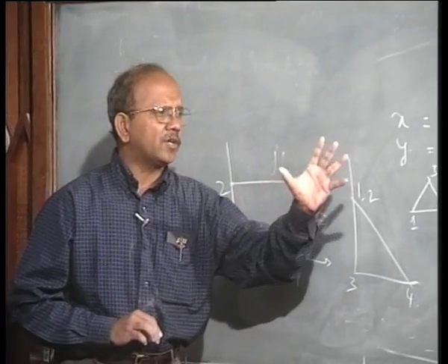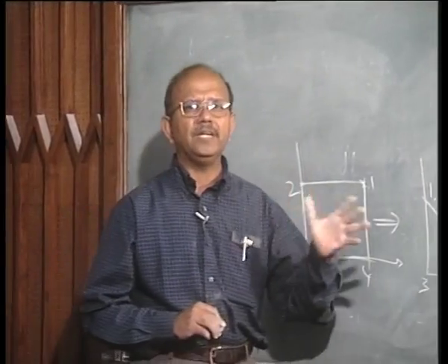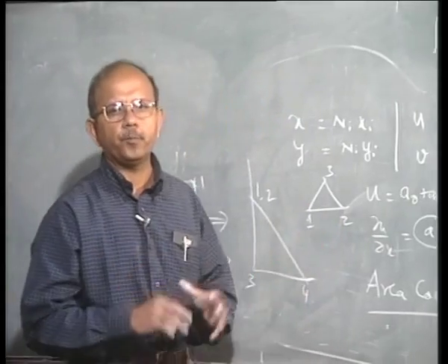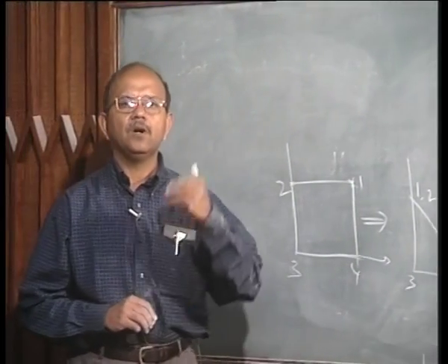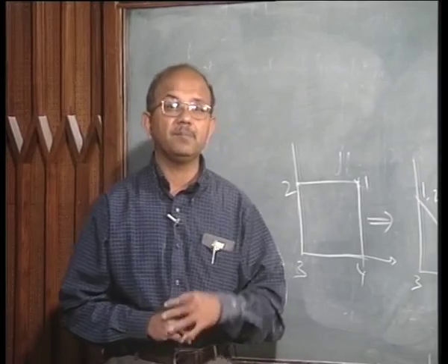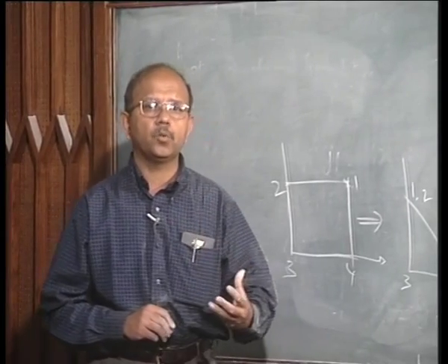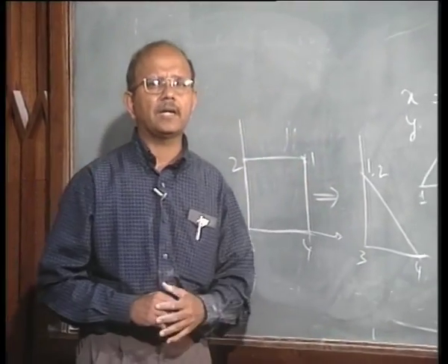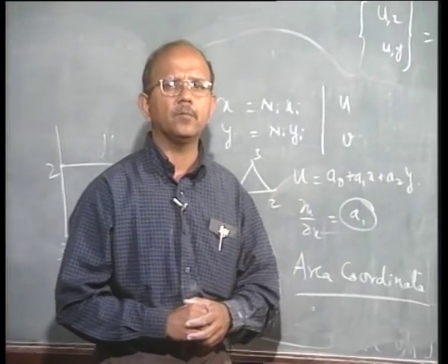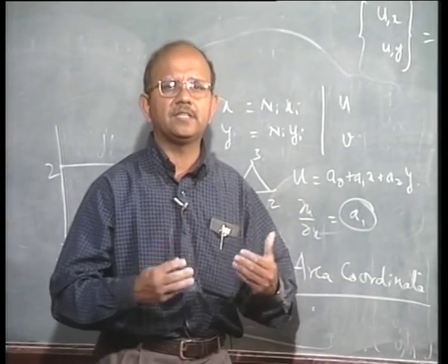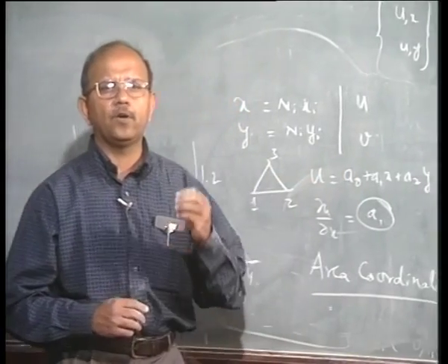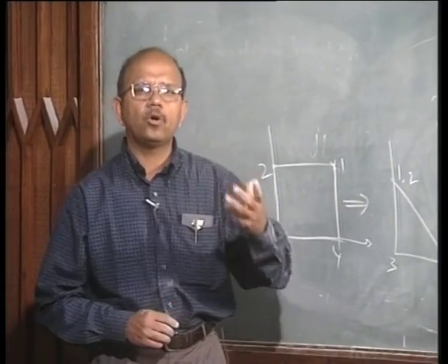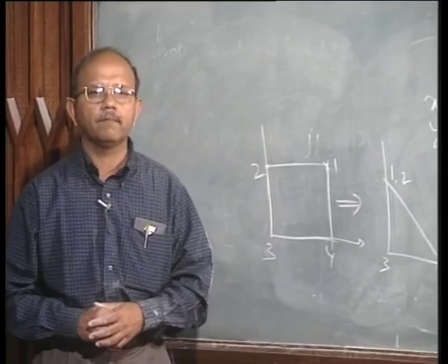Now whatever we have been talking about so far has been for linear elements, but that is not sufficient. I said that the interpolation values can be of a higher order polynomial. It can be quadratic, it can be cubic and so on. Whether it is the quadrilateral element or the triangular element, it is possible to raise the polynomial degree from linear to quadratic, cubic and so on.